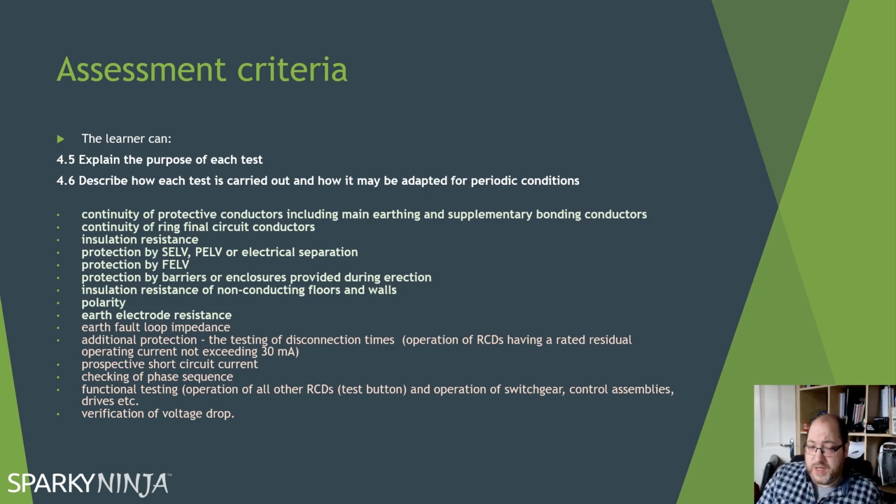With regards to electrical separation, like a shaver point or anything like that, if it's only one item, that's fine. But if we have electrical separation feeding 2 items, we have to segregate them from everywhere else. FELV, functional extra low voltage. You may see this in control panels and in some factories, but again, it's more a case of segregation, but for the purpose of function. It's not for the purpose of protection.